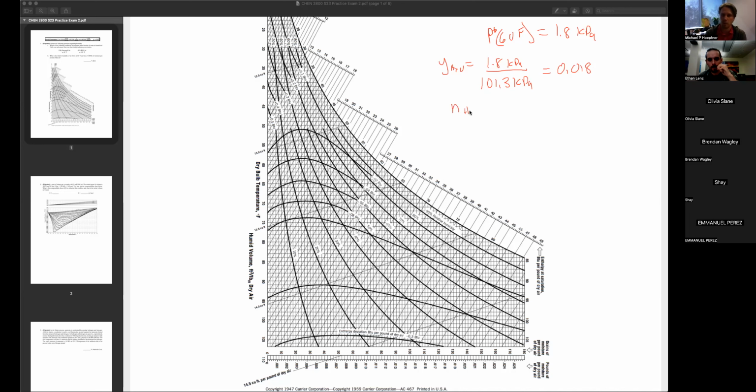And this is number of moles of water divided by number of moles of water plus number of moles of air. I choose 1 mole of dry air. And then we can solve this one here for the amount of water. So I'm trying to get this to an absolute humidity. But I can use that because that one's an easy reference state here.